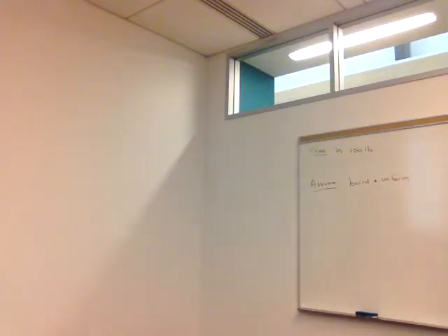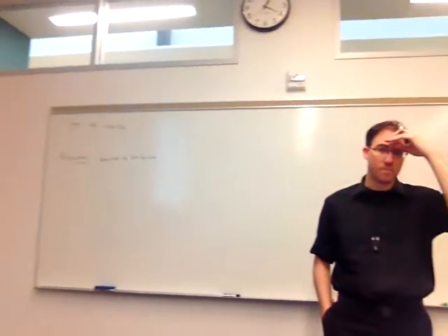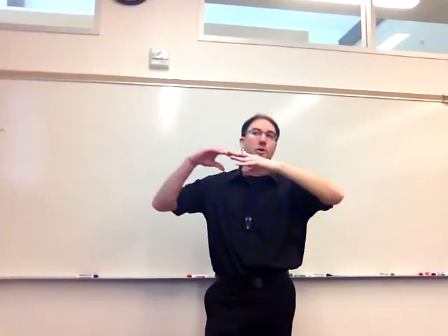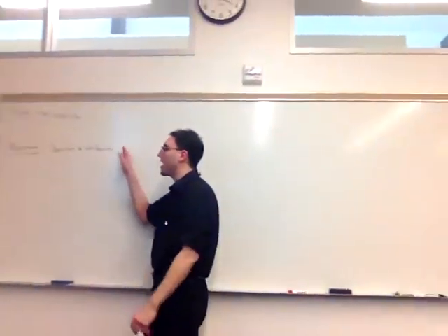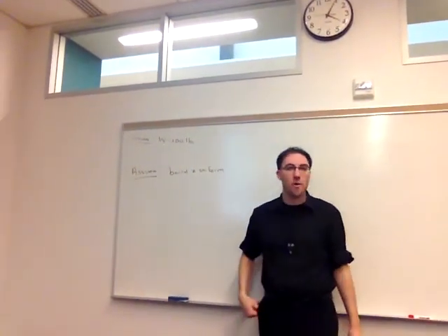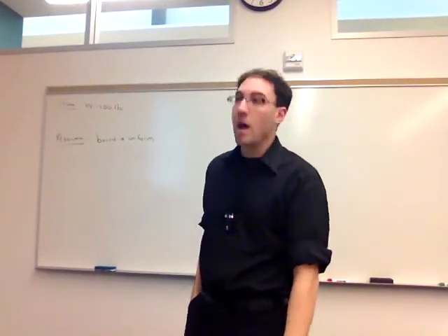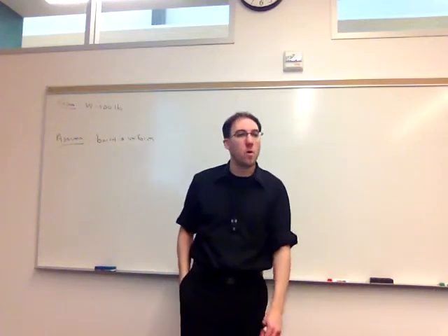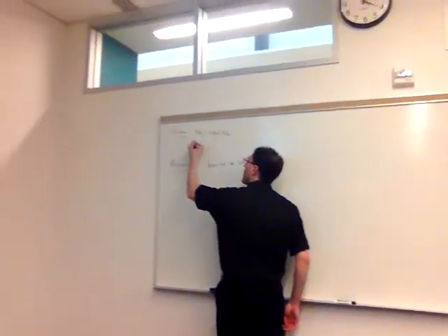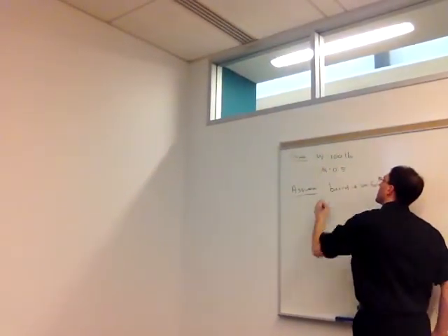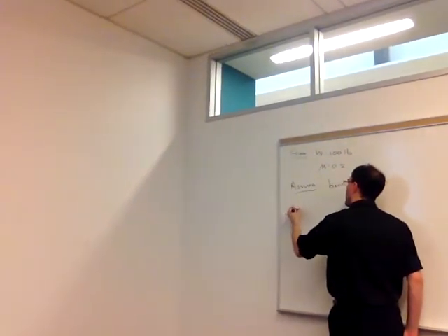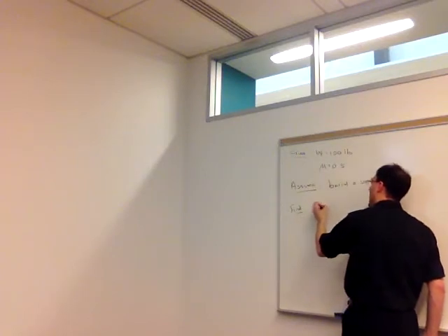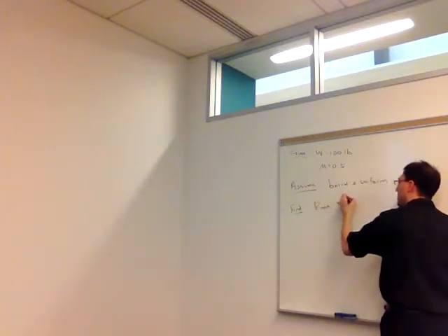And now let me put the weight of the barrel in its geometric center. If I had more information that it was filled with water halfway up or something like that, then that might change. But without that information, I'll just say it's uniform and analyze it that way. We're told that between the barrel and the floor, the coefficient of friction is 0.5. We want the minimum value of P to cause motion.